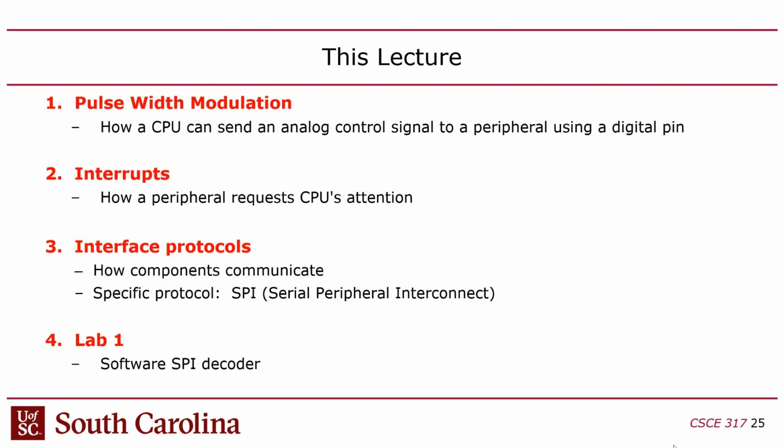So normally with programmed I/O, that's all driven by the software, right? Software does reads or writes to hardware, but the hardware just responds to it. It just responds to programmed I/O. The problem is that if that's your only mechanism, there's no way for the hardware to initiate communication with the CPU, and that's what interrupts do.